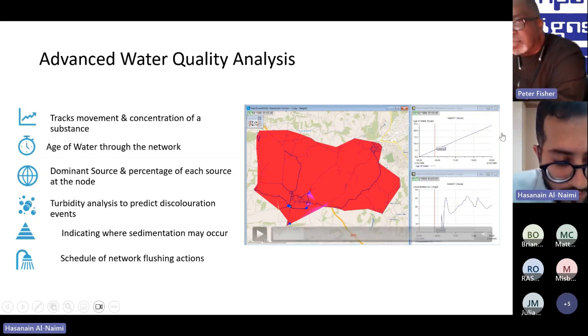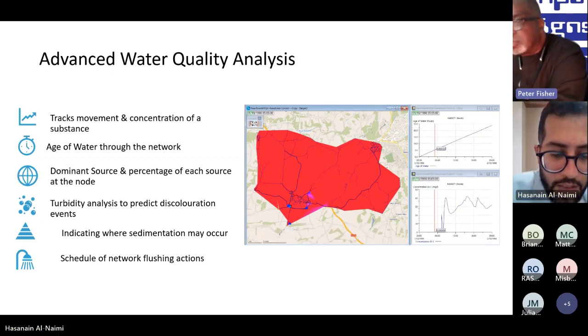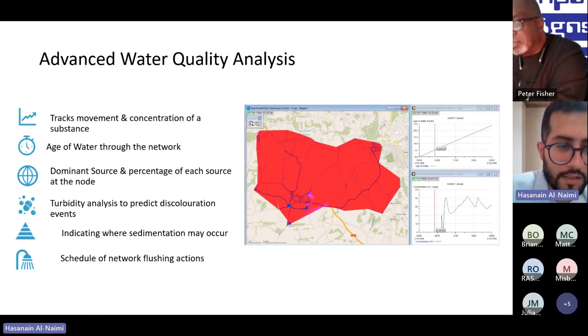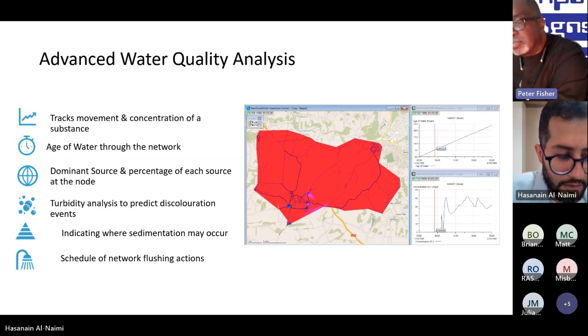On the pumping line, if you have a new pipeline, as it ages, the internal roughness of the pipeline increases and requires more energy. The frictional losses increase because of that increased roughness, and the pressure head needed to force water along the pipeline increases as the pipe ages.